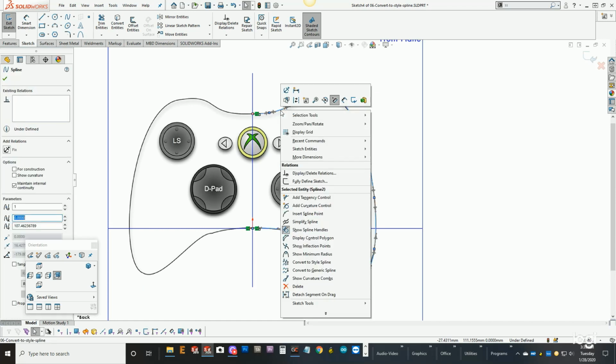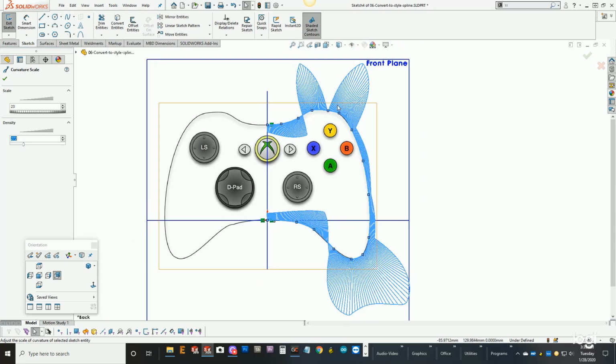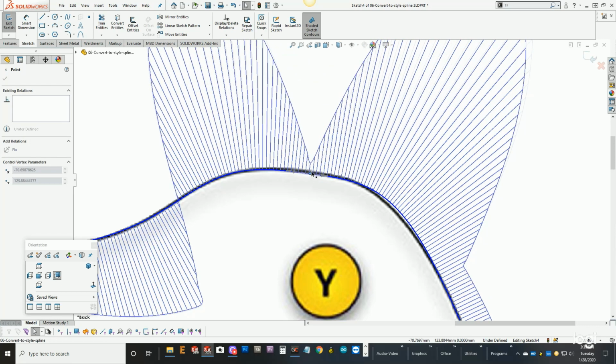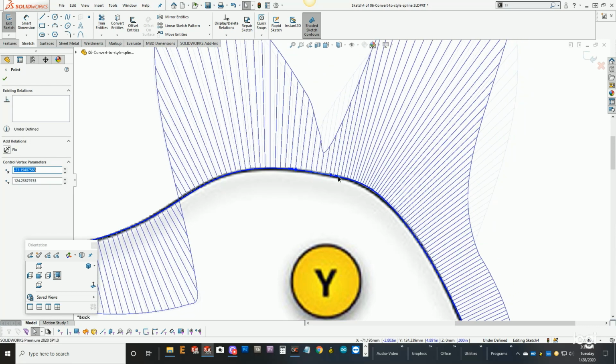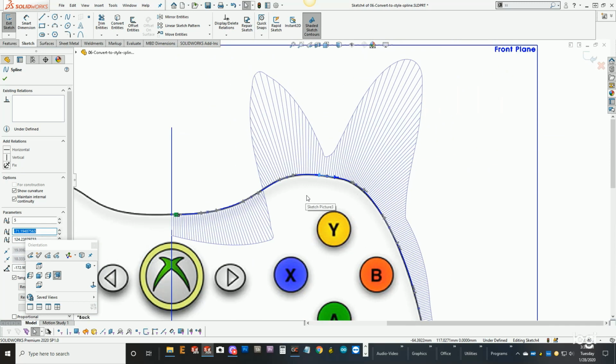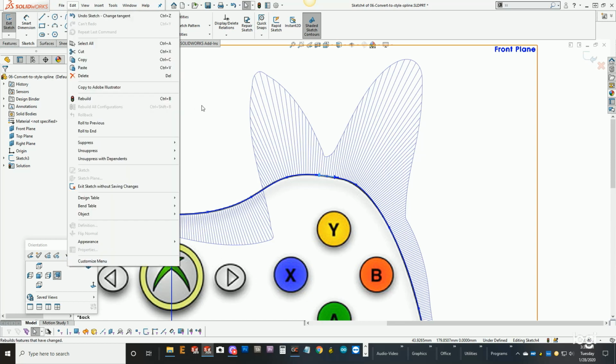If I turn on the curvature display, through-point splines have a harder time maintaining internal curvature, and you can see that right here with this point, especially when you start to manipulate their points. Then it becomes very hard to control them and get a smoother result. Versus the style spline, if I can go forward,